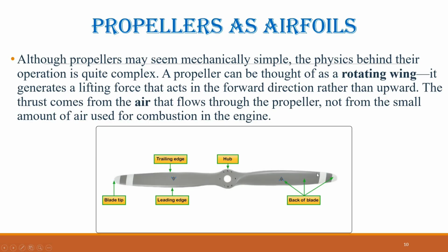Each blade of a propeller acts as an airfoil, just like an airplane wing. When you look at a cross-section of a propeller blade, cut perpendicular to its length, you will see a typical airfoil shape, curved on one side and flatter on the other. Propellers usually have between 2 and 6 blades, and these blades are long, thin, and carefully shaped to ensure aerodynamic efficiency.